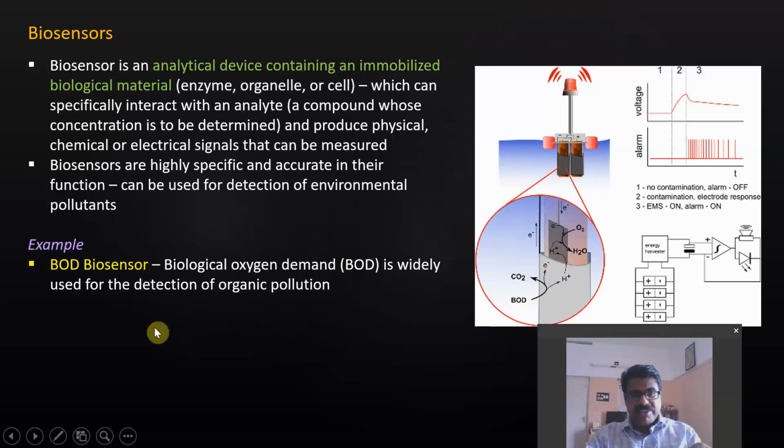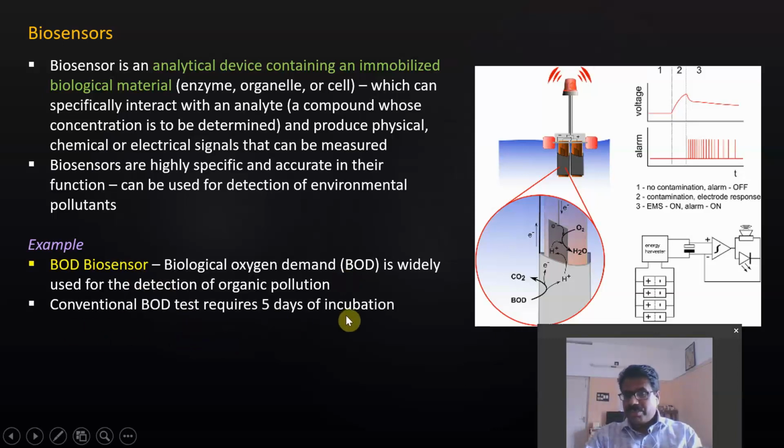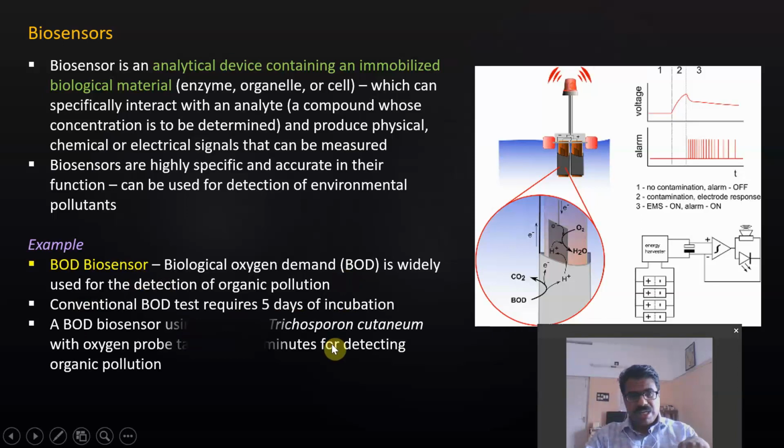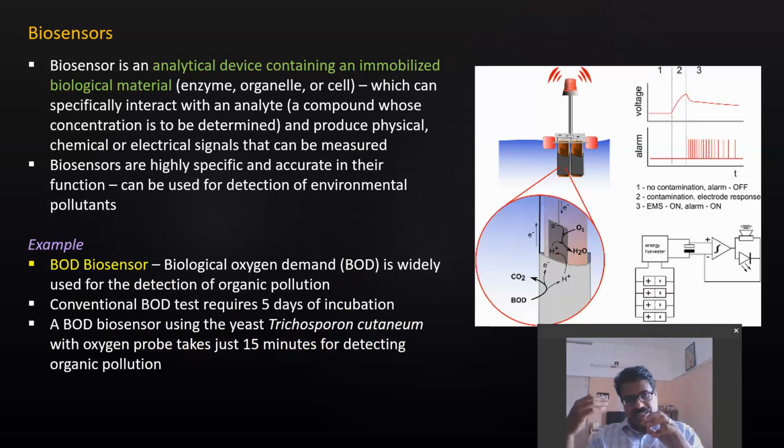But using a BOD biosensor, with the yeast Trichosporon cutaneum and an oxygen probe, it takes only 15 minutes to detect the organic pollution. Instead of one week, we get the result in 15 minutes. That is the use of biosensors, technology integrated with a biological system.